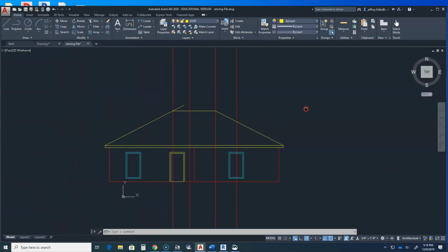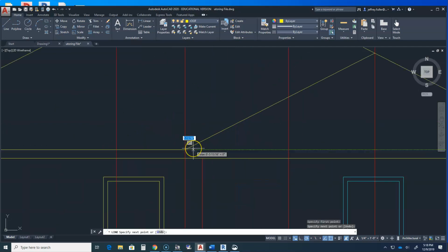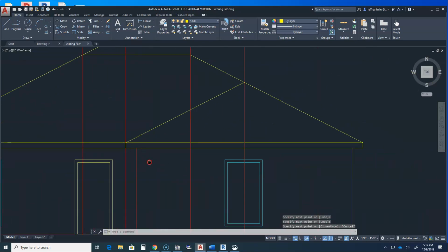Now, what about these other construction lines that mark the setback of a wall and the ridge line of my gable in the front? From here, what I do is draw another line from the gable apex, which is marked by this fourth construction line, down to the intersection of the second construction line and the top of the fascia where the setback is marked. After establishing the second point, I continue a vertical line down to the bottom of the fascia to indicate the setback of the fascia itself.